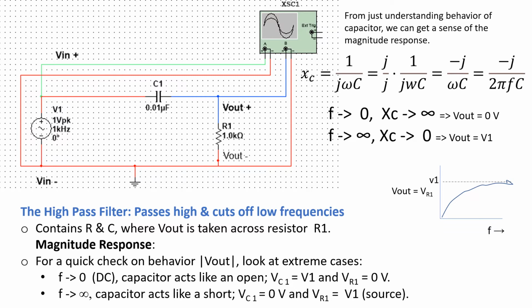When the frequency term is 0, the voltage source is essentially a battery, which we've seen in our DC analysis of circuits. In a DC circuit, the capacitor would charge until it was at the same voltage as our source voltage, and at that point the current would stop. The charged capacitor would then act like an open circuit.